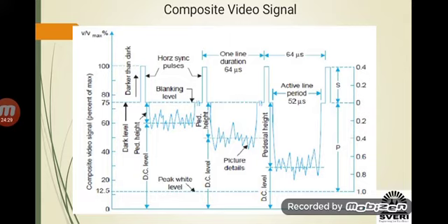In order to provide ultimate cushioning to the electron beam, so that it will decelerate, then reverse its current, and then start scanning the next line, we need to give a certain amount of time, and that is why 5.8 microseconds is required for the back porch. And that is how in totality, 1.5 plus 4.7 plus 5.8, we have 12 microseconds as the horizontal synchronization pulse.